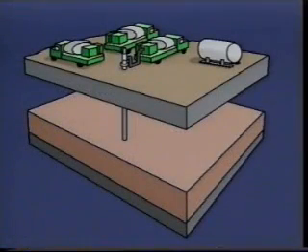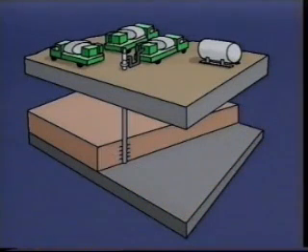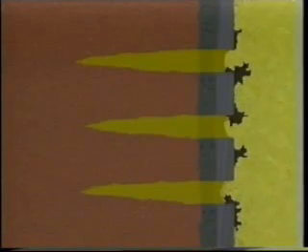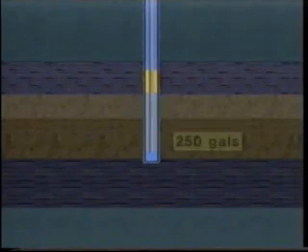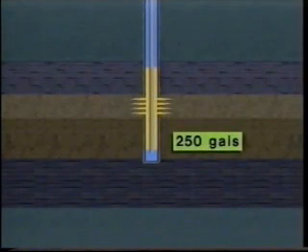An acid wash treatment removes debris from within the wellbore and the perforations. Acid does not penetrate the formation. The procedure consists of putting acid in the wellbore and allowing it to dissolve the soluble material. Acid may need to be agitated or circulated back and forth over the perforated interval. Also, since it is difficult to accurately spot or place a small volume of acid, 250 gallons is generally considered the minimum.